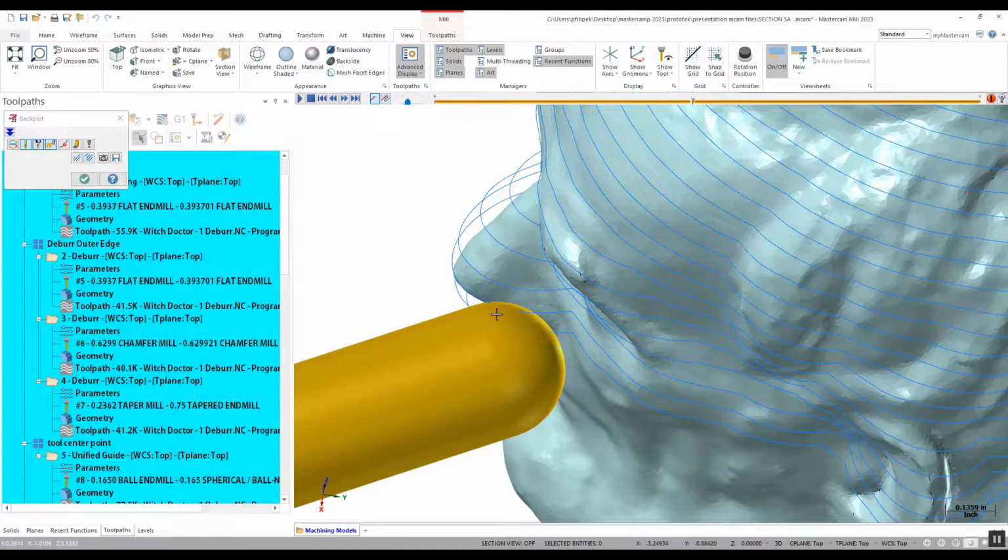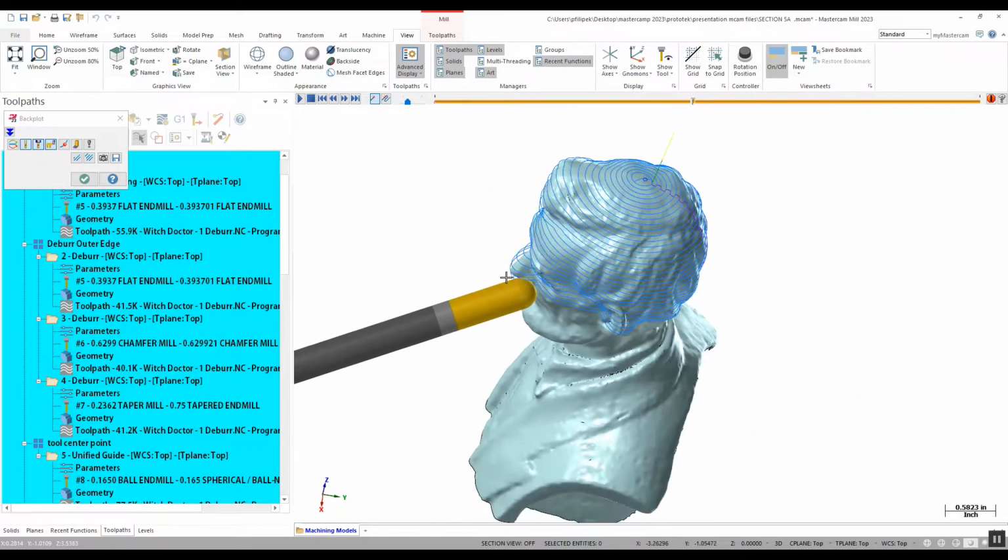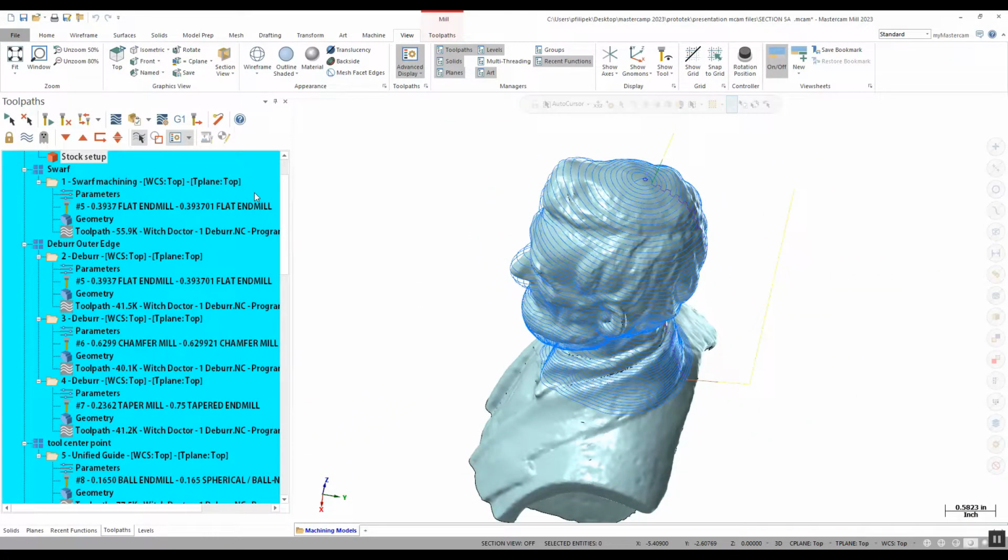So with normal to mesh, the first one we did, we had a better pattern, but we were reversing over. The second way with clean core, we got the motion, but now we're not really cutting the way we would want to cut potentially in some of these specific areas. So we have two tool paths where I want a little bit of that and a little bit of that one. And we don't have really much of an option for that until now.